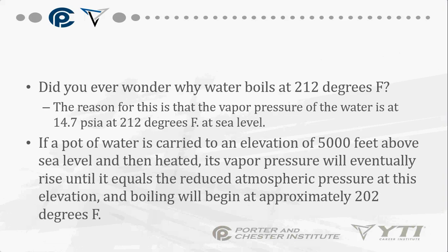Did you ever wonder why water boils at 212 degrees? Well, the reason is that the vapor pressure of the water is 14.7 psia at 212 degrees at sea level. So, let's go to Colorado. Is Colorado at sea level? No, it's higher.